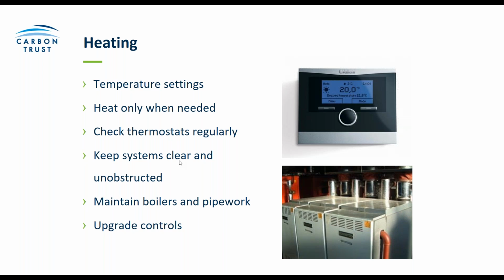At the same time, you may want to look at something like an optimum start controller, which is essentially an intelligent control system that will learn how quickly the building reaches your target temperatures, and then will program itself to bring the heating on at the optimum time before the building's occupied.